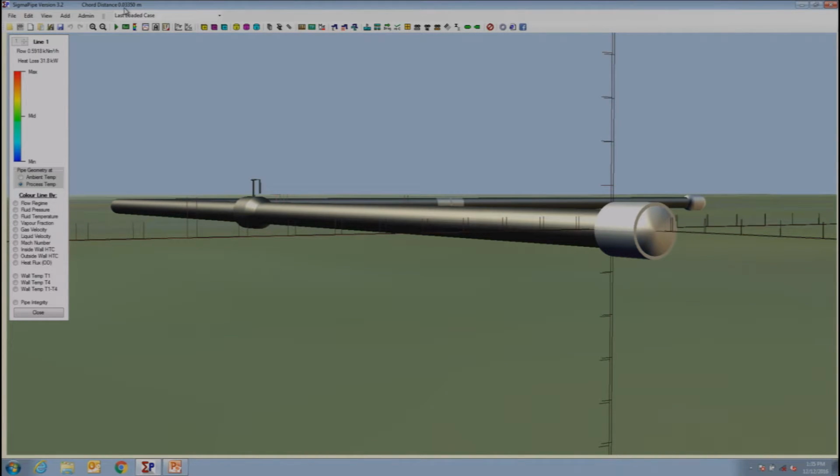Because it's in two axes, it's roughly 20 millimeters along each line that the pipe has physically grown under the influence of the temperature that is picked up from the process gas. If I want to, I can define fixed points and linear compensators and come up with some estimate of what kind of compensation is needed to accommodate that expansion. One of the worked examples does that. I don't propose to go into that here.